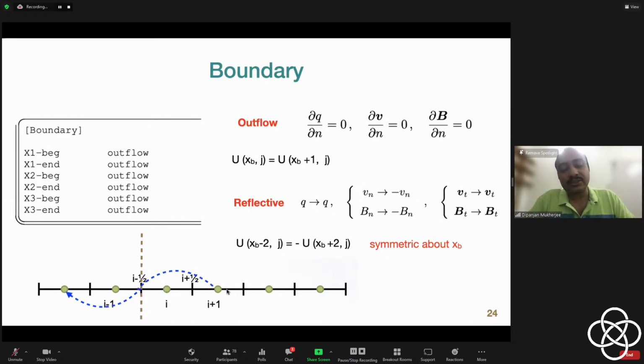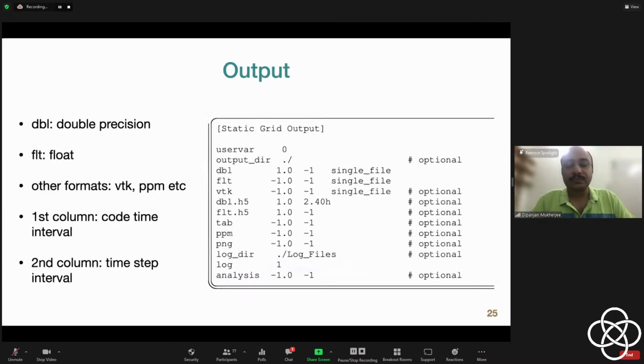What this ensures is if you have a positive velocity here, the velocity goes through 0 here. And then the boundary condition is such that the continuity of the velocity component is maintained, but it is 0 here. So that is why it becomes reflective. So at the point of impact at the boundary, the velocity is 0, and this negative velocity will then cause this wave to get pushed back in the other direction.